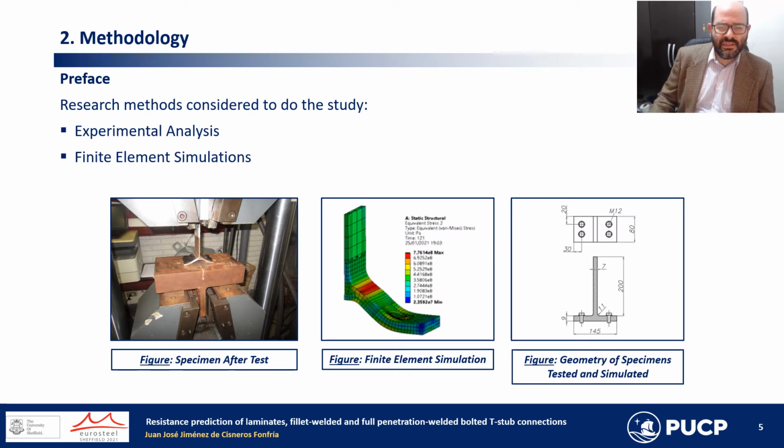The analysis has been performed by two different methods, experimental and by finite element simulation. The same geometry was tested with three different web-to-flange connections, one continuous, one fillet-welded, and one groove-welded. In the case of the experimental works, two specimens of each topology were tested.